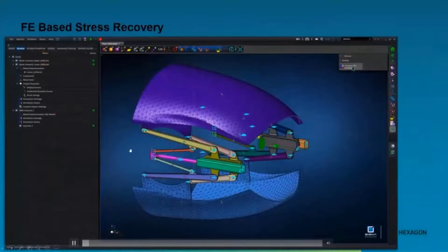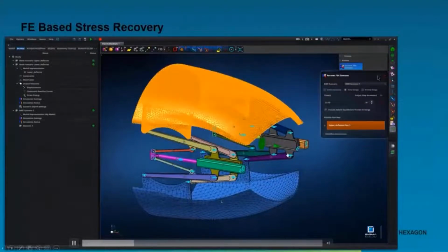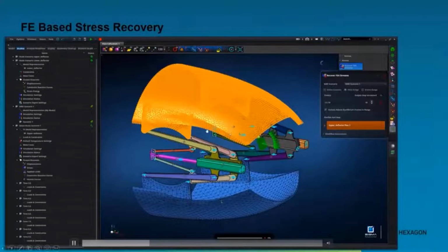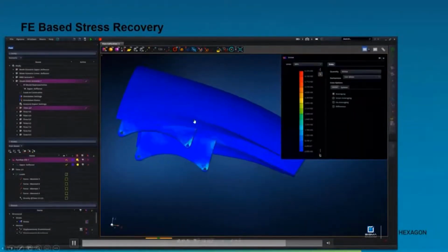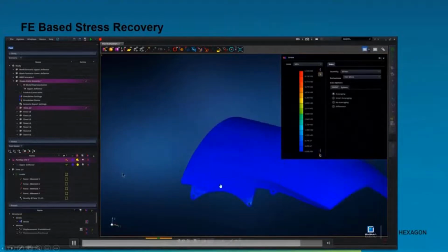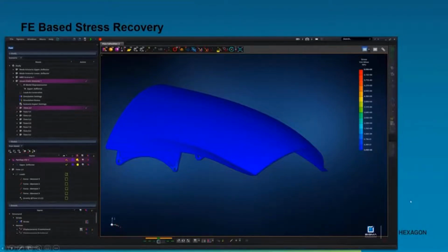Again, stress recovery is also very important if you're doing some fatigue analysis. So getting the modal participation and the stress histories at these locations becomes very important. So that is also more user friendly. And once you have done this, you can look at the component level also, how the stresses are getting generated. Even in Adams Flex, we were addressing only linear, but in this environment, we'll be addressing one more level of higher fidelity.